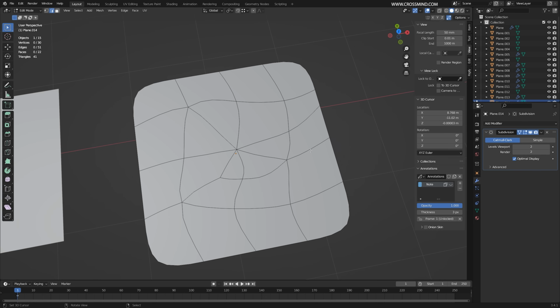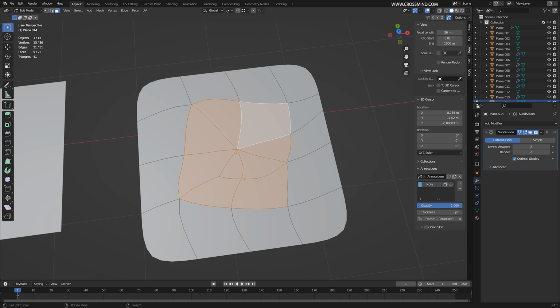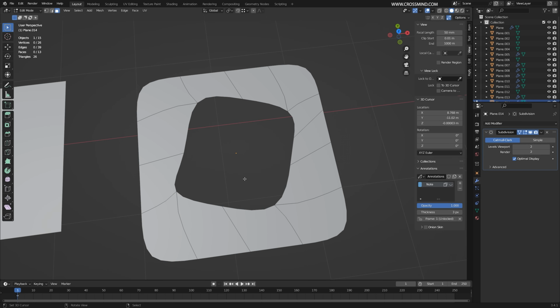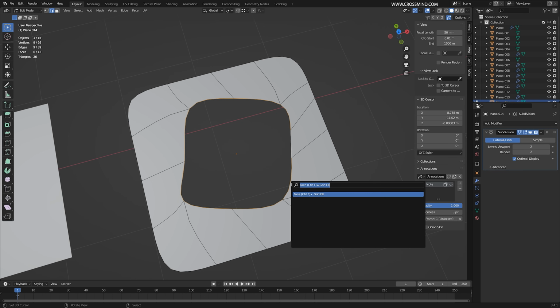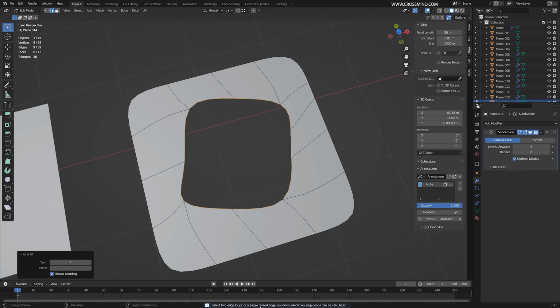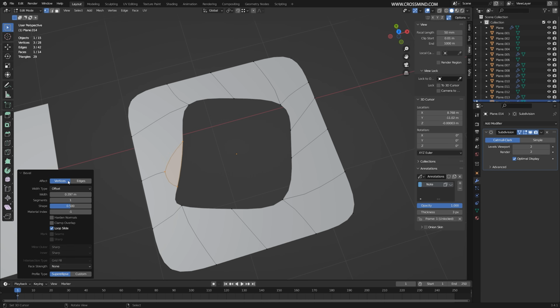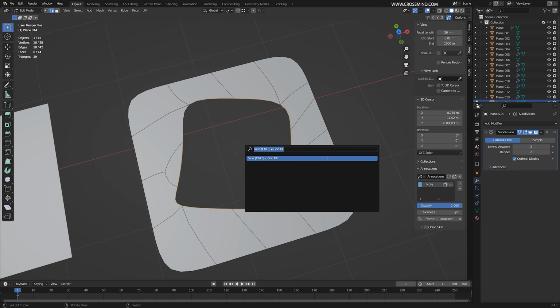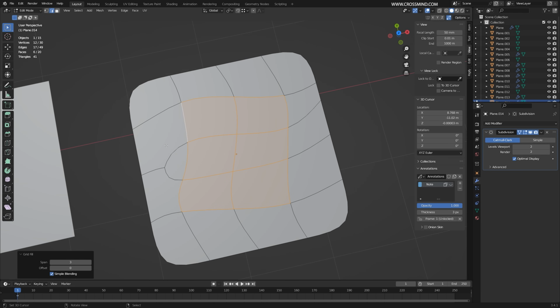Now there might also be scenarios where the mesh doesn't really make sense. There are just a few loops making no sense. So instead of fixing these, sometimes you can just use a simple grid fill. Just get rid of this face and then grid fill. If it says you need an even number of vertices, you can just bevel one of these vertices and then you have grid fill, which works for you. And then you can fix this one.